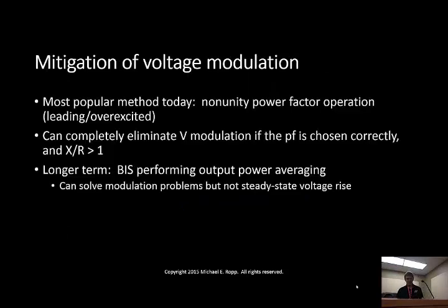And we've seen some anecdotal stories of where the number of tap changes per unit time for a regulator jumps up by a factor of 5, maybe even a factor of 10 in some cases, after a PV array goes in. And usually the reason we learn about it is because 6 months after the PV plant went in, the regulator fails. So obviously this is an issue that we want to try to take care of.